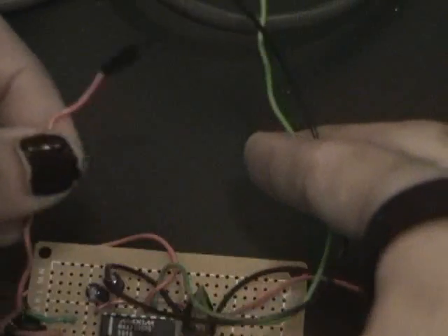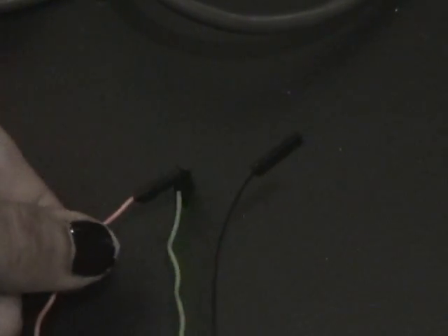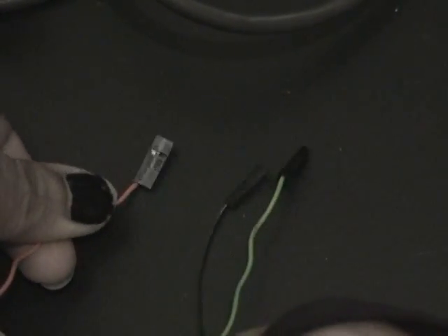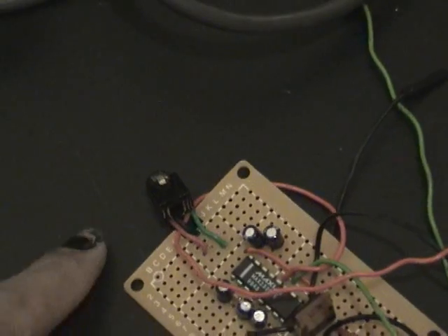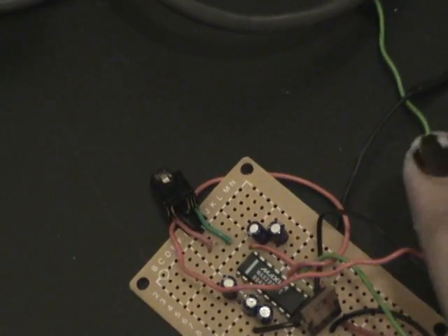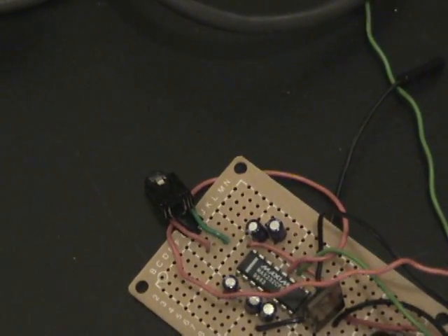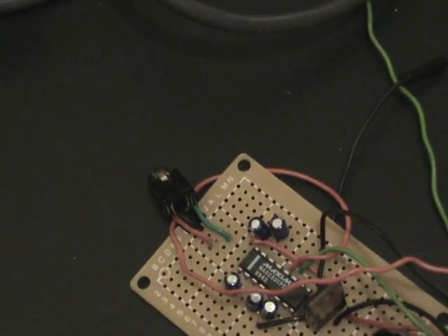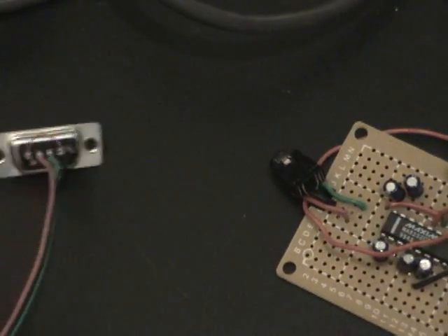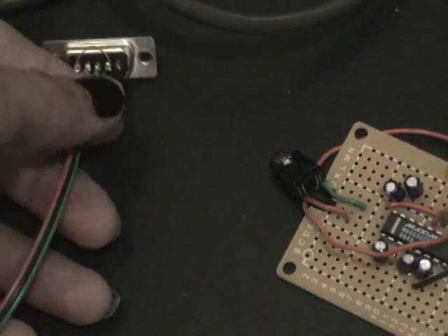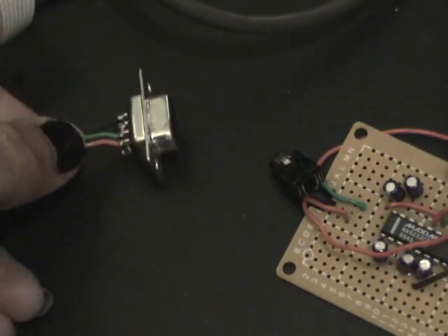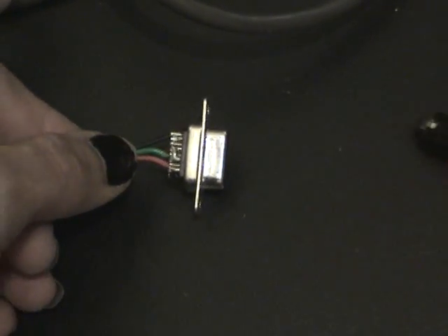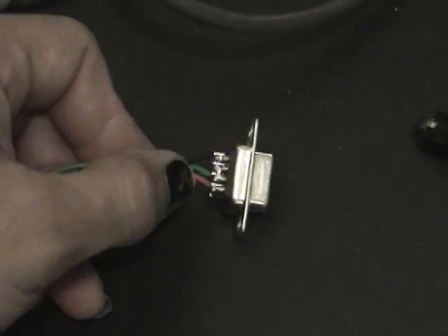To interface into the actual hardware, I used stereotypical pin headers, same things that you use to hook up the LEDs and power switch to your computer. This all actually will output to a headphone jack. Reason being is because this is a very simple null modem configuration, meaning that it does not require data carrier detect, data terminal ready, data set ready. I'll try to get a nice zoom in of this header right here.